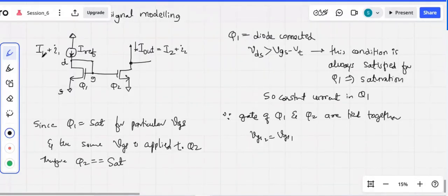Now, before that, why have we written here capital I1 and small I1? This is basically a DC and this is basically an AC. Remember, whenever we try to generate the currents, or play around with the current and voltage signals in our entire MOSFET related circuit, you should ensure that you are mentioning both AC and DC. It is only during your AC analysis that you short the DC sources, and in the DC analysis you ignore the AC sources. But invariably, the current or the signal or voltage values, whatever you are seeing, are a combination of AC and DC, because there will always be two sets of voltages and currents in your entire MOSFET circuitry. The DC sources act as your biasing sources, and AC sources basically act as your actual input and output sources.